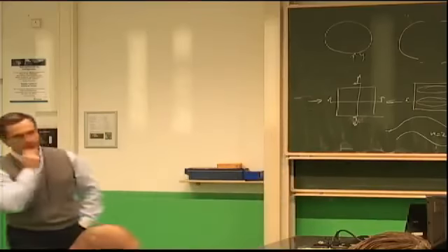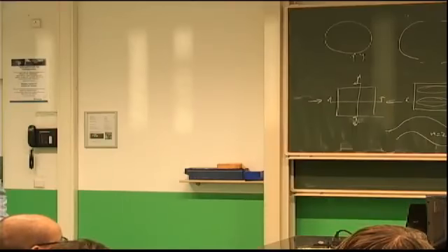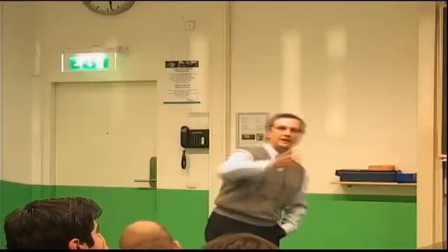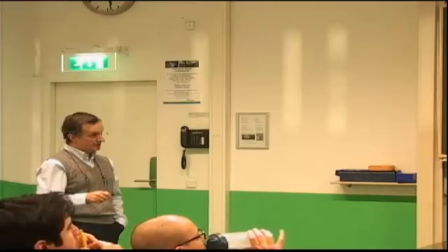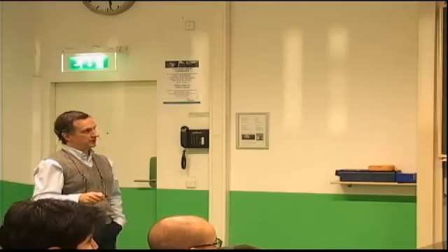How would that compare now to an equal thickness aluminum? Aluminum is much better. Basically, it can be anywhere between 10 to 20% better. The exact same equations we derived for composites can be used for aluminum. You just set your E values equal in all directions, and you rederive your ABD matrix, which is much simplified. Then you can use the same equation and get the curves for aluminum, which have the exact same shape, one half wave up to 1.4 or so, and two half waves up to 2.4. Keep in mind, for aluminum, these are exactly the curve.